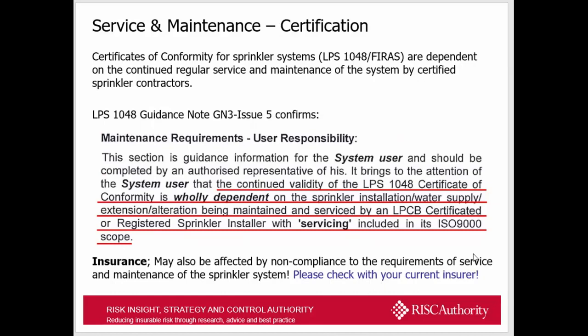So, certification. Certificates of conformity for sprinkler systems can either be the LPS 1048 certificate of conformity, or a completion certificate, or the FIRA certificate. They're dependent on the continued regular service and maintenance by sprinkler contractors. So if your sprinkler system has been awarded a certificate, it is only valid provided that there is a service and maintenance regime in place by a certified sprinkler contractor.